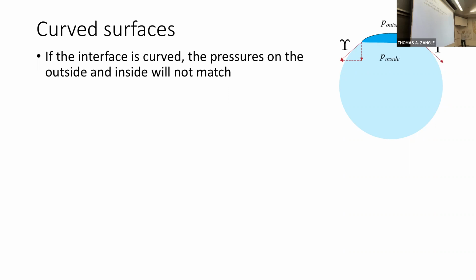But in this case, we also have a surface tension force caused by the molecules on the surface of this droplet binding to each other, holding tightly to each other, exerting a force per unit length to hold together. They don't like being cut apart, for example. They're holding together like a skin on the surface of this droplet. Imagine almost like the elastic skin of a balloon. That's basically what we have at the surface of this droplet. It's just water, hydrogen bonding to itself.